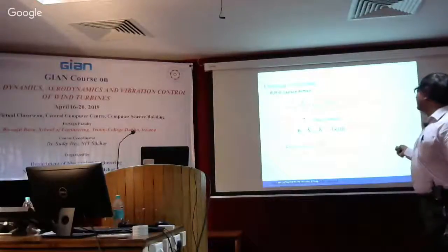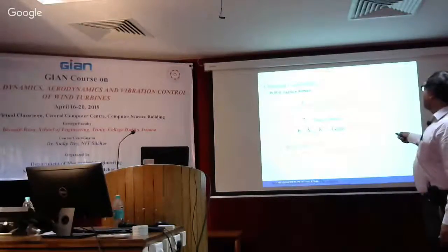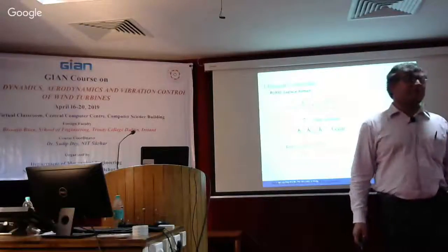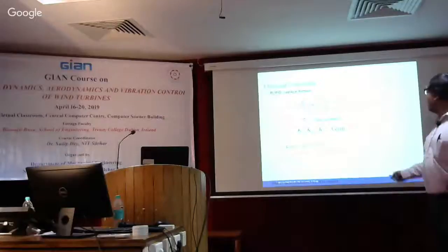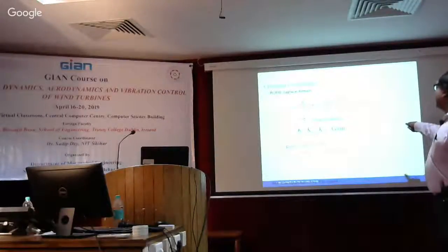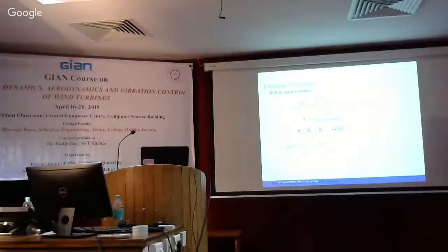And this is a classic PI type of controller, but not in the time domain, but in the Laplace domain. And you can see that this is your integral controller. If you take the Laplace transform of an integral, then you get 1 over s. The proportional factor gives you kp, and then here you have the derivative, so that's why you get s over here. Those who are aware of the Laplace transform, it transforms the time domain response into the s domain, which converts the differential equation to an algebraic function, essentially. So converting the problem to an algebraic domain, and then solving the algebraic equations is obviously easier, and then you design the performance or the dynamics in the algebraic domain to see what the transfer function may look like. Then you can come back again to the time domain.